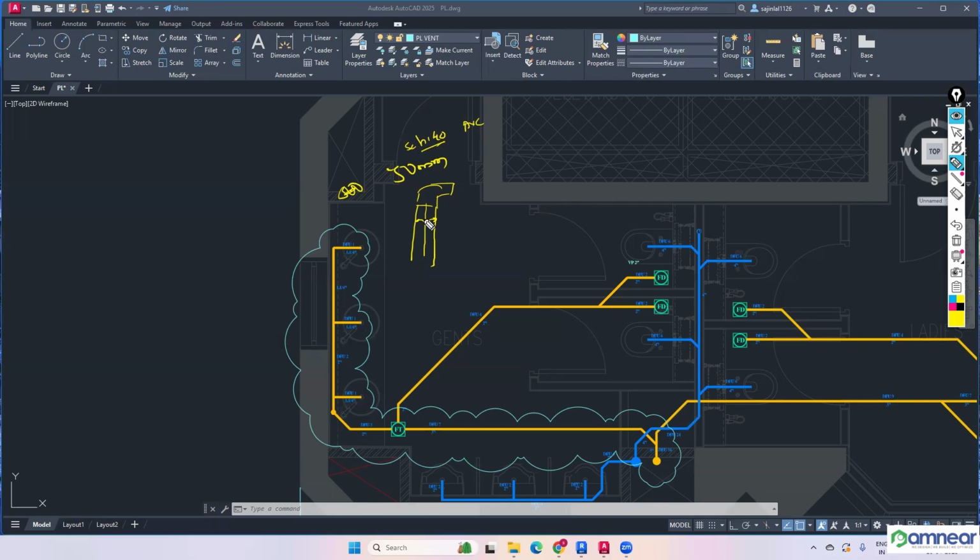So that's why, with respect to the center line for 50 mm schedule 40, if you are offsetting 25 mm and 25 mm, you'll be getting the external outside diameter only. So exactly for schedule 40, 50 mm, the outside diameter is not 50, it will be slightly higher. So that is wrong, but still people are using it for easy work, and they will be following the same method.